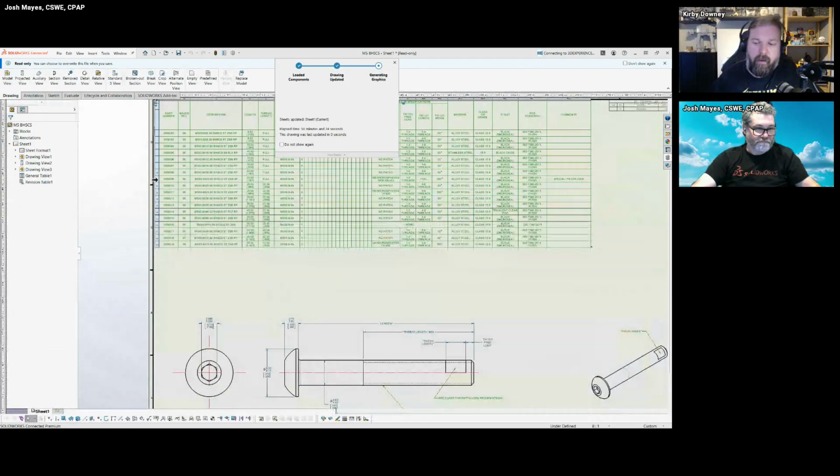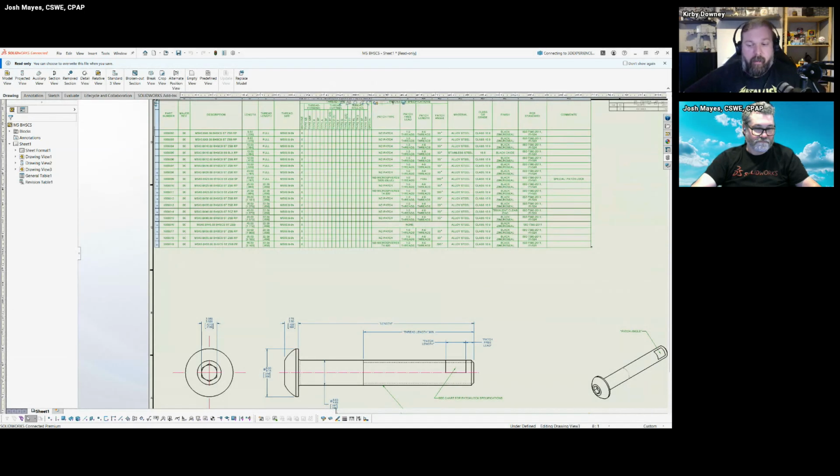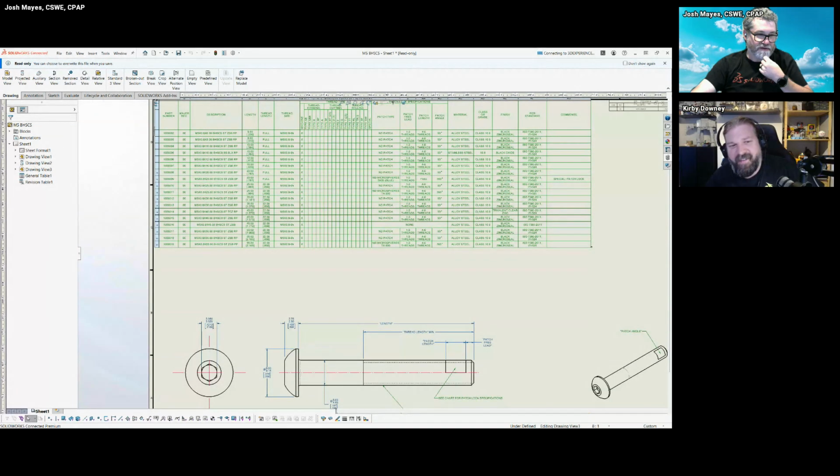I haven't seen any. I mean, Craig has basically said when working with PDM, make sure those fields are all read-only. On the data card? Yeah, which I think, indeed. Yes, that could probably cause some chaos. Your data card is going to display those fields and allow you to search by them, filter by them when you search, but you don't want those to be edited at the card level because obviously that's not going to come back and edit your design table necessarily. Nor would you want it to. You really want it to be a one-way street. You want the design table to drive when you're using them.